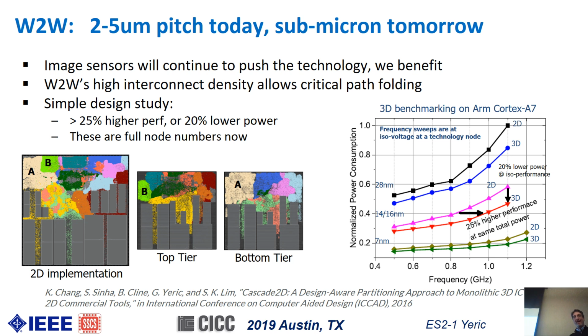If you can intelligently take a CPU and fold it into 2 tiers where you're getting rid of the long wires that are the delay problem, you can get really impressive performance improvements out of this wafer stacking technology. I'm expecting 0 to 10% improvement in performance per node. Call it 5%, right? Nothing really exciting per Moore's Law node going forward, but you can get a really nice boost of, say, 20, 25% by shortening paths to 2 layers in a 3D sense.